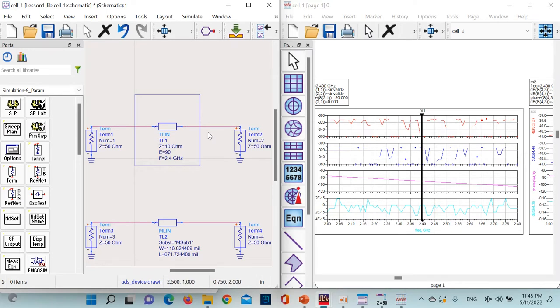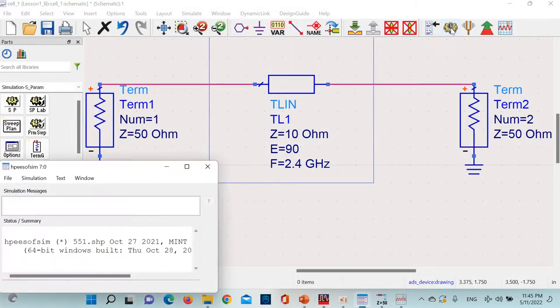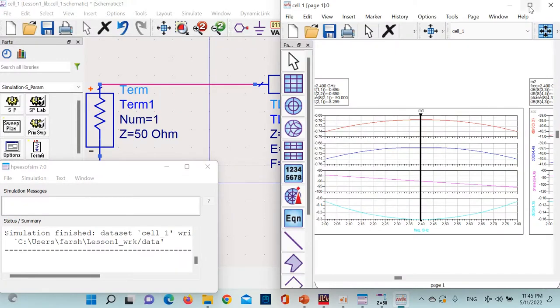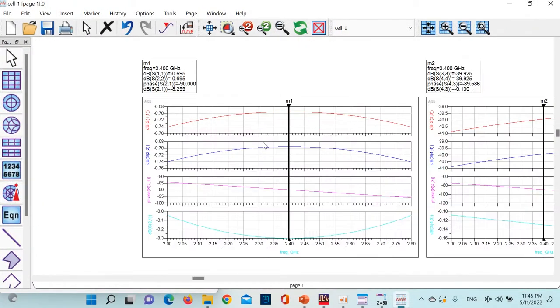Bad means worse than what is showing right now, right? Let's simulate it here. I push on this and let's check it out. Yeah, look at it. It's terrible. In dB, it's not better than minus 25 dB anymore. So it's bad. It's showing that you have mismatch, right?